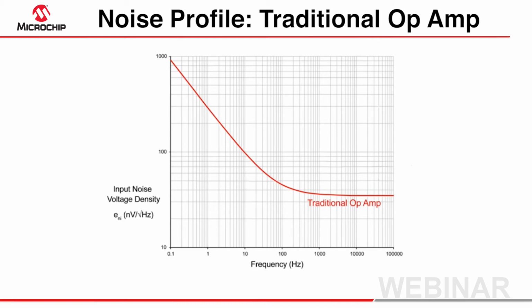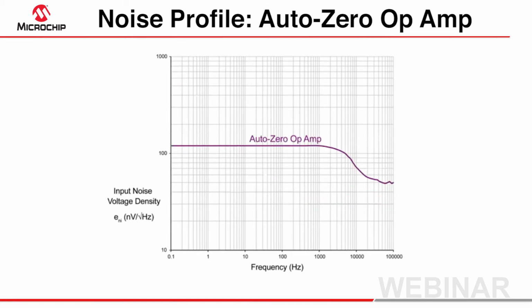In most cases, the filtering will affect the signal as well, and the low filter frequencies require either very, very high resistance values, leading to higher thermal noise, or large capacitor values, which are physically very, very large. A more practical solution for this dilemma is the zero-drift amplifier, which virtually eliminates the 1/f noise, as mentioned earlier.